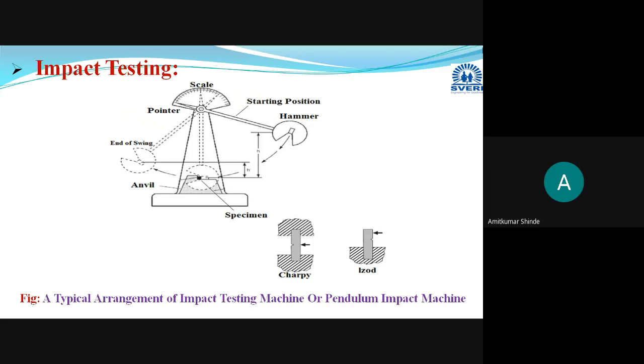If you observe the brittle material, a flat surface will be there. In a ductile material, the crack will appear as a cup and cone surface, due to the formation of the neck.